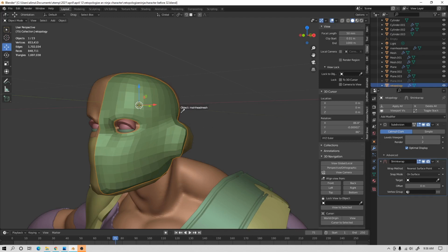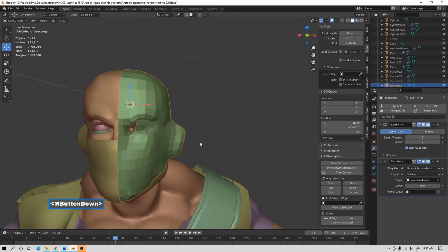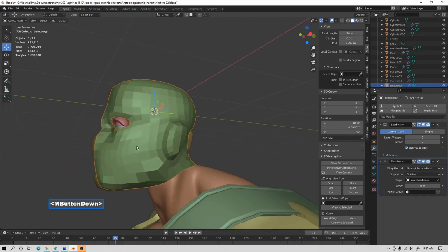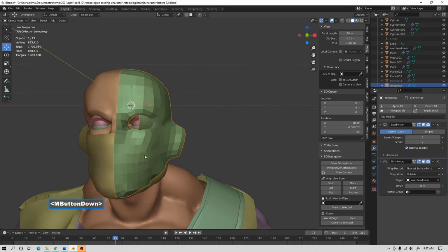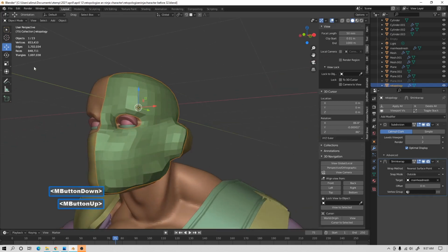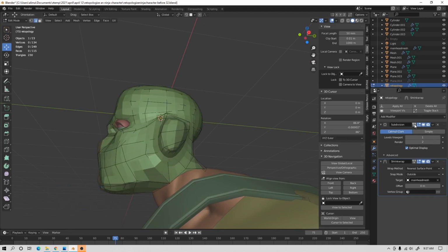There we go, the main head mesh. The ear goes in, right? How do we deal with that? We change this snap mode to outside. Now the ear comes out. Why did we take off the mirror modifier? We took it off because it's fairly easy to put on, and I find that it causes issues. See this right here? We're going to go to edit mode. We'll select this triangle to the right, and select the shrink wrap there.